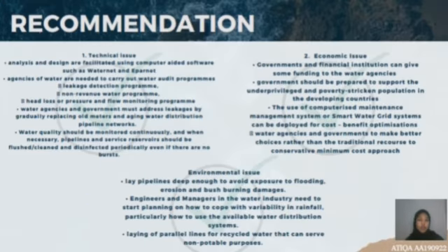Recommendations. First, for technical issues, it is highly recommended that analysis and design be facilitated using computer-aided software such as WaterNet. Next, water agencies are needed to carry out water audit programs such as leakage detection programs. Other than that, water quality should be monitored continuously, and when necessary, pipelines and service reservoirs should be cleaned and disinfected periodically even if there are no bursts.